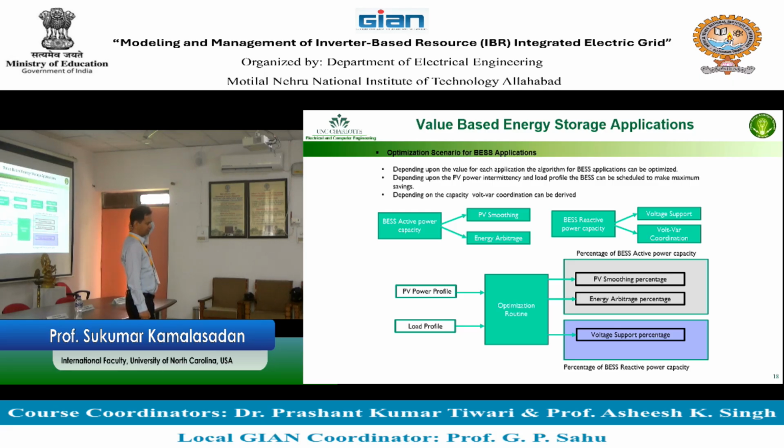Do you want me to explain a little bit? Okay. Voltage support means you are making the voltage at a point and maintaining that voltage constant. That's what we just explained in the previous slide. For maintaining the voltage constant, you need reactive power. But the reactive power that you are supplying is changing. What is important is to maintain the voltage constant. This is called voltage support. So what will be the output reactive power from the inverter at that time? Some number. It's changing all the time. You don't care about that number.